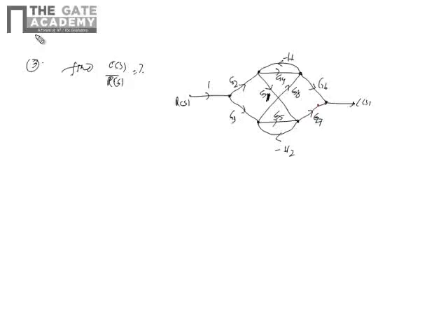Fine. So here, how to find out the K value? Once you find out the K value, then you can easily use the Mason gain formula. G2, G4, G6, 1 is one path, and G3, G5, G7 is another path. Then G3, G8, G6 is another, then G2, G1, G7 another path, and one more, G3, G8, H1, G1. So finally you will get the K value as 6.